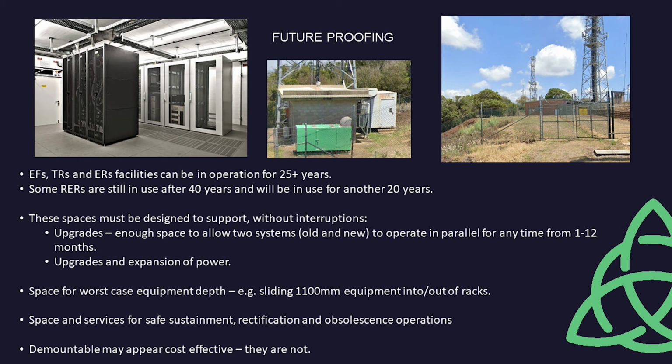For equipment rooms and dedicated entrance facilities, emergency exit lighting should be provided to guide egress in the event of power failure. The layout must be initially designed to maintain the following minimum clearances around the equipment racks. The front of rack to wall needs to be the depth of the rack plus 300 mm. Enough clearance to install full-depth equipment in the rack. The back of rack to wall needs to be the width of the rack plus 100 mm.